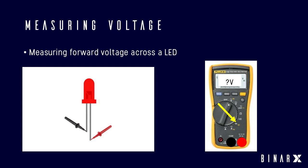Do you want to show them how to measure it with a multimeter as well? It's got a diode mode on it. Oh, does it? Okay, I didn't know that. I actually haven't ever used that. It's a good check because it'll measure the forward voltage. So when they get back to their seat, they can check it. Yeah, I'll give it a shot. I'll just try it before I do it.